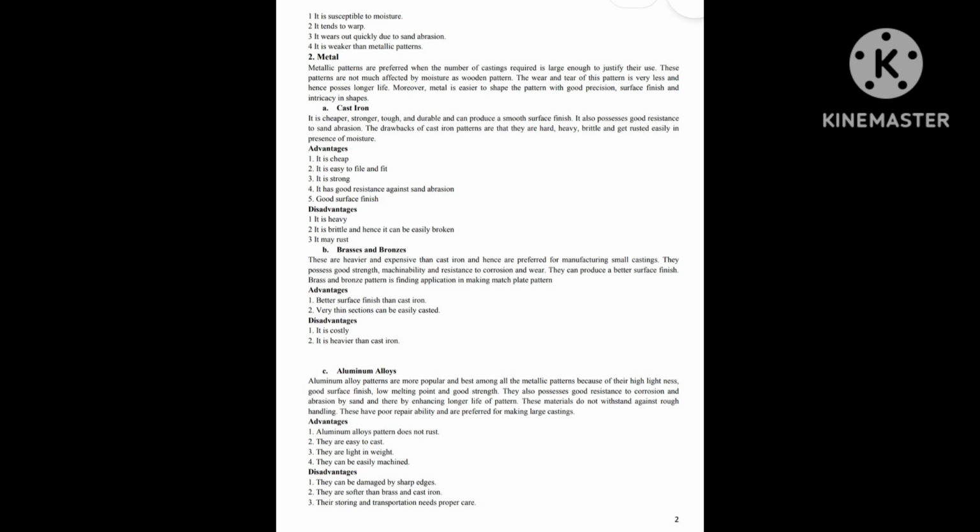These are heavier and expensive than cast iron and hence are preferred for manufacturing small castings. They possess good strength, machinability and resistance to corrosion and wear. They can produce a better surface finish. Brass and bronze patterns are finding application in making match plate patterns.